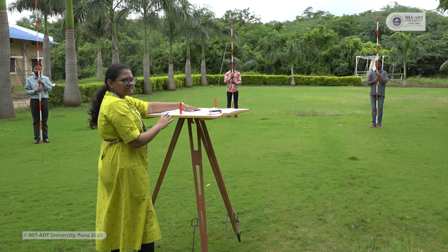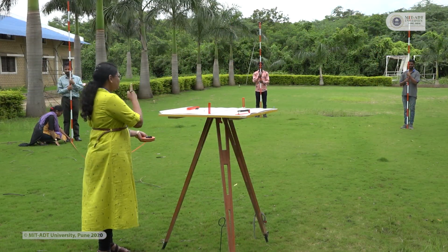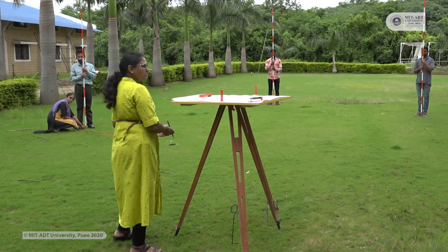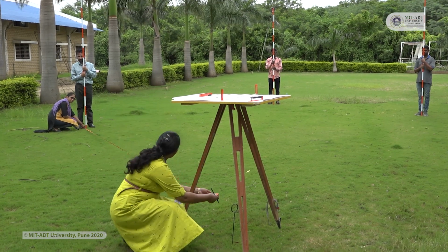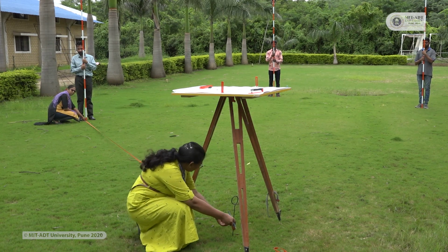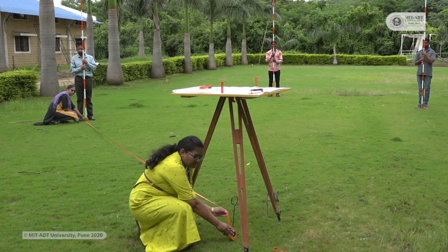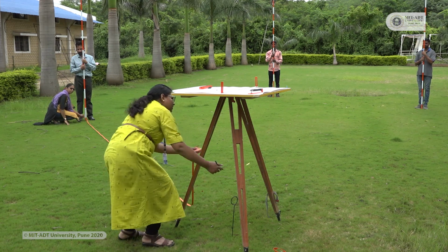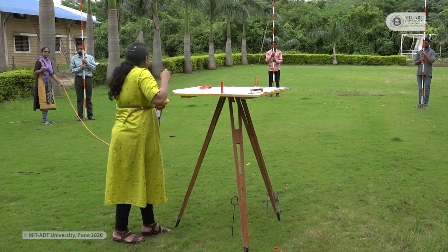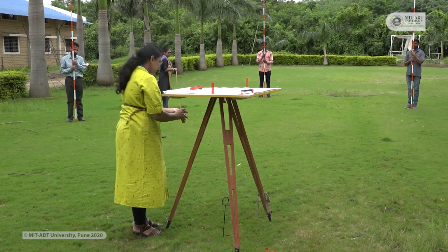Now we have to measure the distance between these points by using the tape. After drawing the rays for the 3 points which we have to bisect, we will measure the distance by using the tape. First we will measure the distance between the 2 station points. Make sure that there are no undulations on the tape. You have to keep the tape very straight. This distance I will mark as 7 meters and 30 centimeters. This is the distance for our first point. I will write down the distance here. Then we will measure the distance for the second point, which we also measure with the tape.